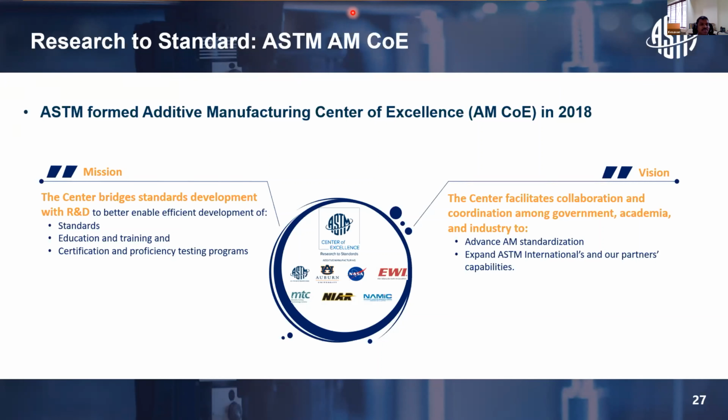Yeah, this is quite interesting. Let's say the machine is from the same manufacturer, OEM, and the material supplier is also the same. You are printing the same material, same component, same machine, but the only difference is the location. Still you are seeing a difference. And not even the location, but the person who handles it, the atmosphere, the conditions that you have. For example, the moisture conditions. The humidity levels will affect your powder when you go to recycle it, and the way in which you recycle the powder, the number of times you recycle it, the way you handle the powder, the way you store the powder, all those things matter.